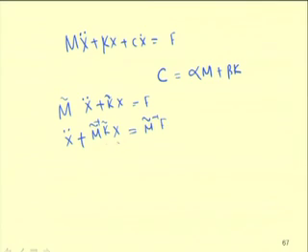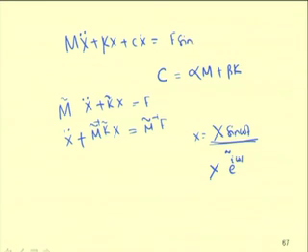This equation can be solved by substituting x equal to x sin omega t, or x equal to x e to the power i omega t. Let the function f be sin omega t, or it may be constant also. In that case, first you convert that to a set of single-degree-of-freedom equations, and then you find the response of the system.